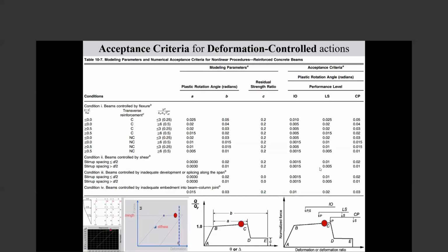But in general, taller shear walls behave in flexure and undergo plastic deformation in the flexural hinges, and the shorter walls will go nonlinear in shear mode, because when they become shorter, they become very stiff in flexure, so the shear deformation increases.